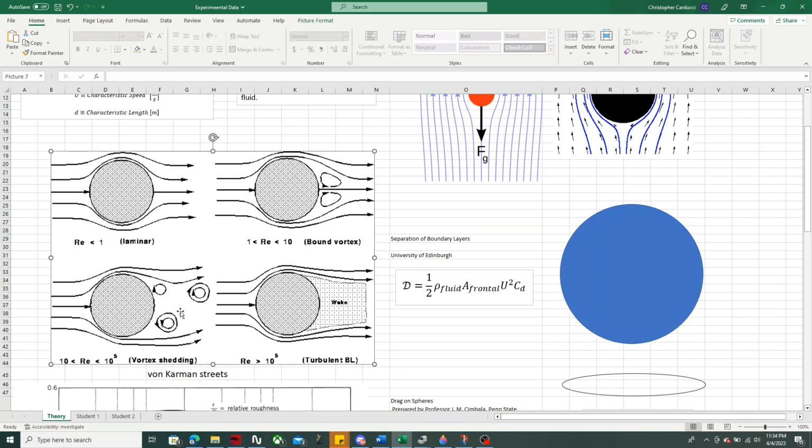But you'll see that you now have to start worrying about things like, okay, well, what does the air do after it leaves the body? So, for instance, when you are moving at pretty considerable speeds, or you're a larger body like a car, you're now worried about the pressure wake behind you. That's where you're going to get most of your drag, most of your energy losses, is the air essentially having to be shoved around you and then fill in the gap behind you, right?